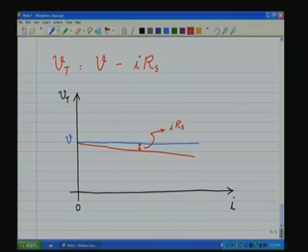So in all practical power supplies or voltage sources, you will see that in the VI characteristic, the terminal voltage is not going to be horizontal, but it will be slightly angled down by an amount equal to I into Rs, where Rs is the source internal impedance which is in series, and this equivalent series source impedance is 0 in an ideal case.